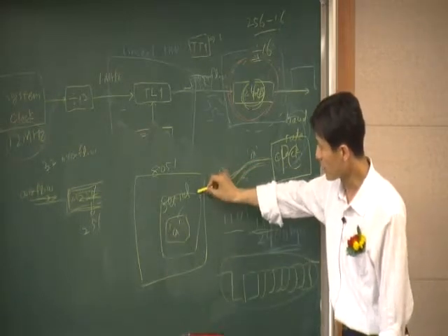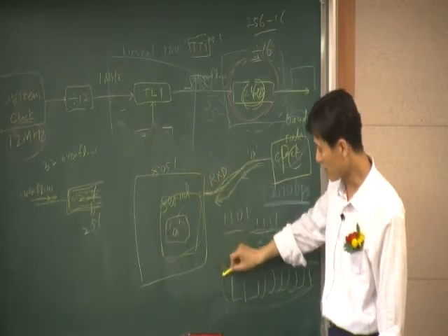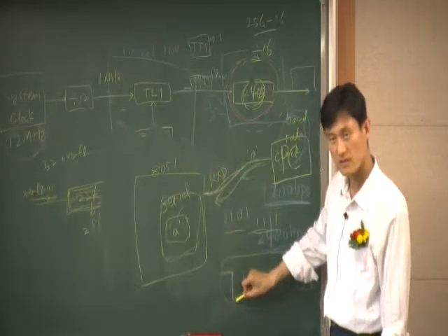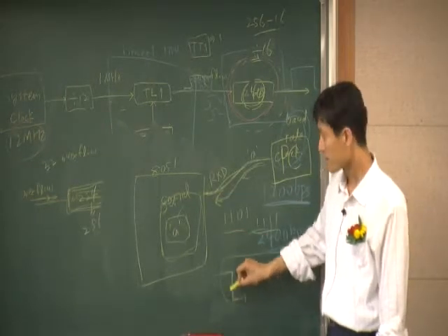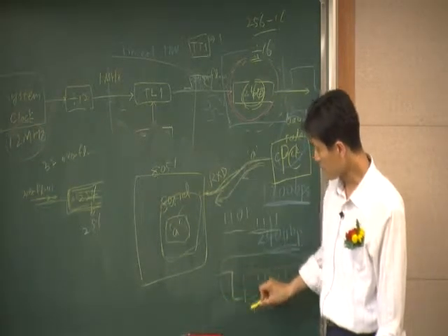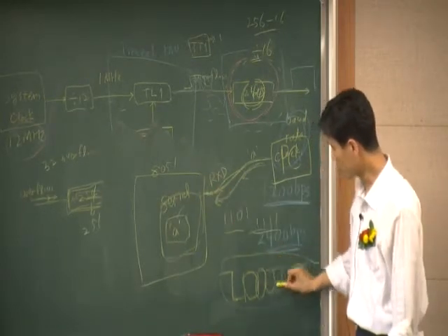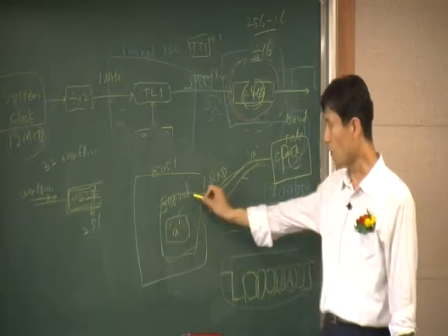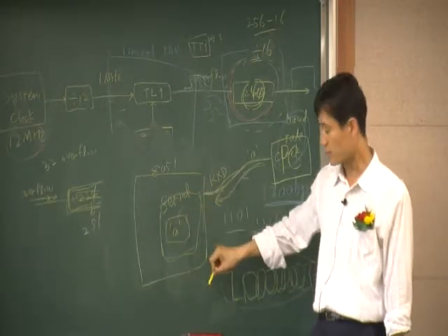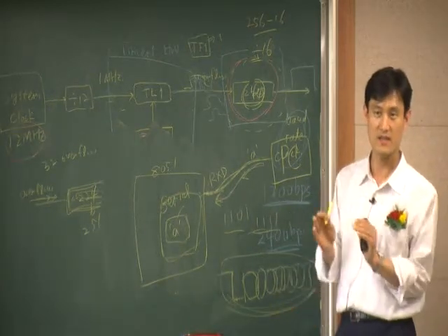So inside the serial communication hardware, what they need to do first is to detect the start bit, right? Once you detect the start bit, then this receive hardware will decode the 8 different bits. That's all done by the hardware. So this kind of thing takes some time. It's not instantaneous.